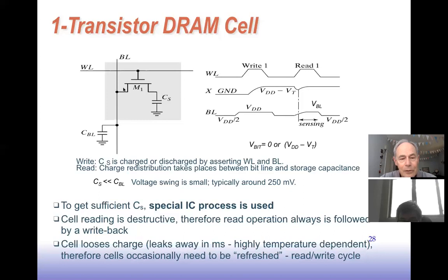themselves, right? Because the voltage across here will cause current to flow. So what we'll see is if the bit line was charged to VDD over 2 and this was holding a 0, when we turn on that transistor, the bit line voltage will drop a little bit because some of the charge that's keeping it at that voltage will migrate over to that capacitor. Likewise, if the cell is storing a 1 and we turn on that access device, the bit line voltage will push up a little bit. You can see that in the pictures here if you want.